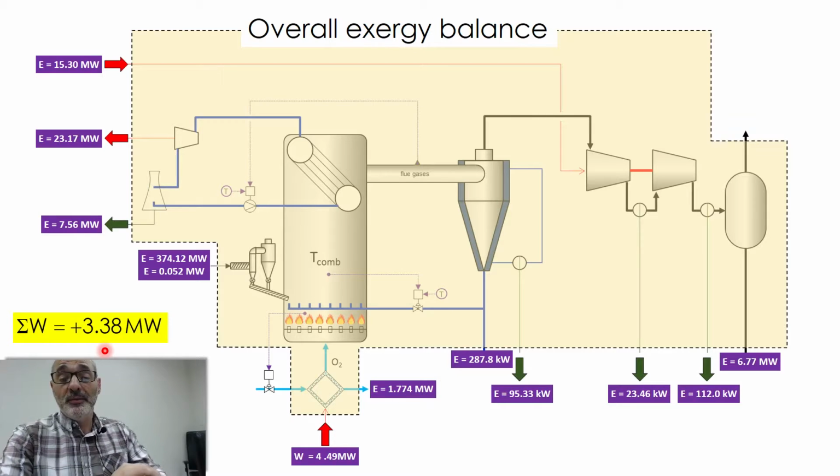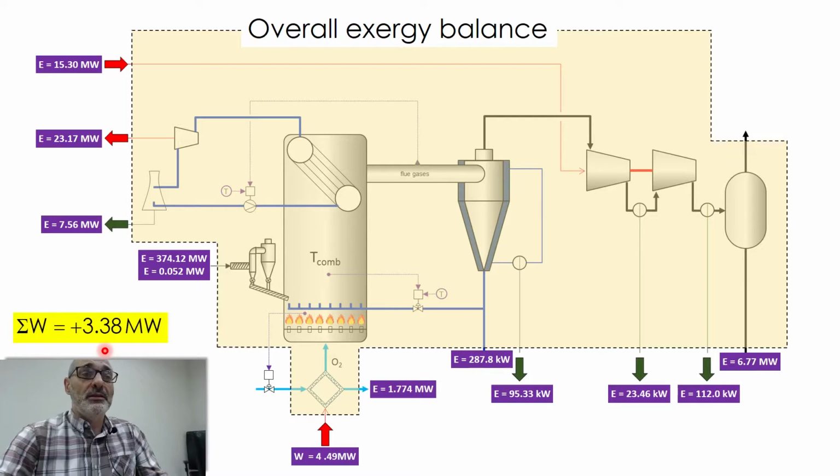So the conclusion here is very important. The conclusion is that you can transform this sugarcane or this oxy-fuel boiler into a CCS machine, provided that your carbon source is from biomass, which captures CO2 from the atmosphere. So you can transform that into a CCS machine and still export electricity. I'm going to show you all the calculations, if I'm not wrong, in our last class.